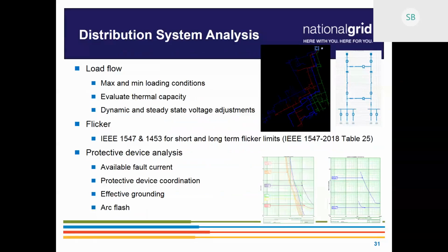We have a company program and mandate where we go through and check the arc flash in all our feeders. So as more DG comes online, it has an impact on that directly. So we're checking that as well for safety of our workers and public.